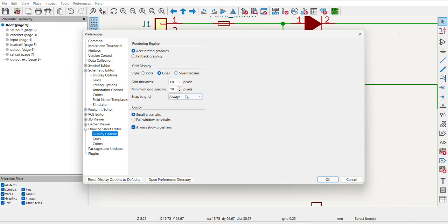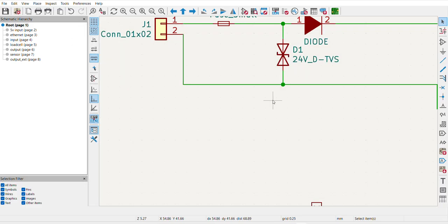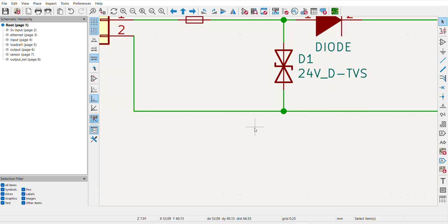It is a very mild tone that I'm setting. In the preferences, the grid thickness is 1 pixel and the minimum grid spacing is 10. Here I can go up to 5 pixels, so I keep the same 1 pixel, or else I will set 0.5 pixels with a grid spacing of 5. When you want it wider, you can give a grid thickness of 1 pixel and a minimum grid spacing of 5. Then click OK, go there and check the design.